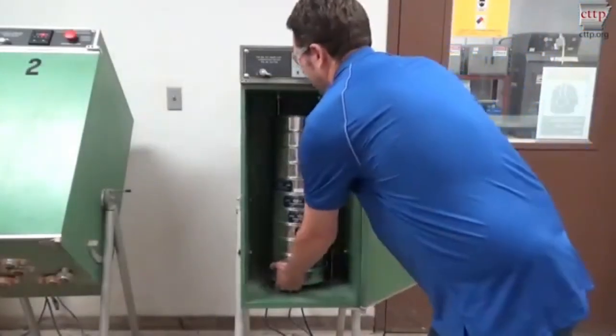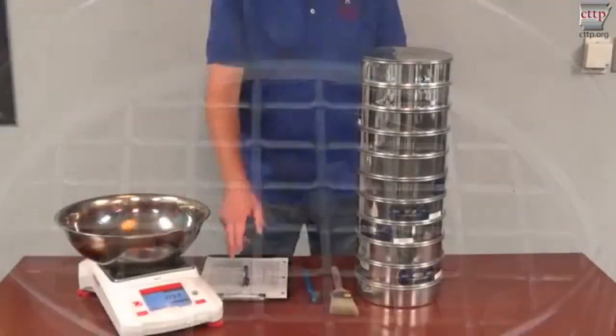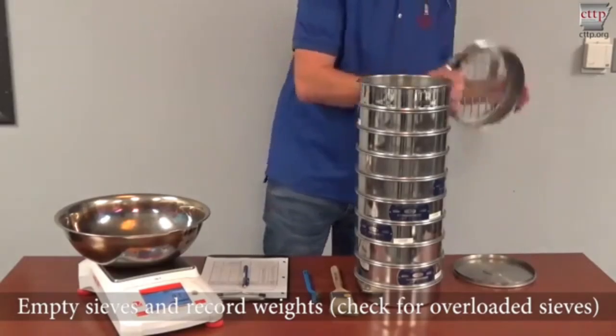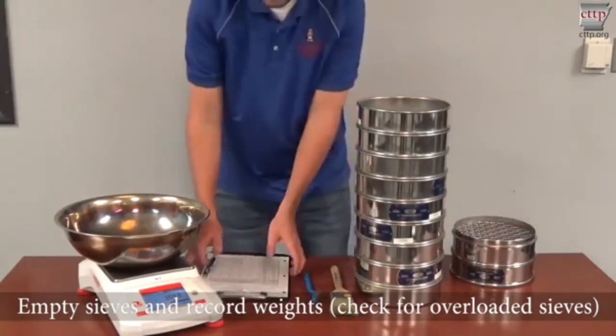After sieving, remove each sieve from the stack. Remove trapped aggregate from undersized openings. Empty each sieve and record the weight of material retained. During this process, check for overloaded sieves. Note that individual or cumulative weights may be recorded, and the method chosen will affect subsequent calculations.